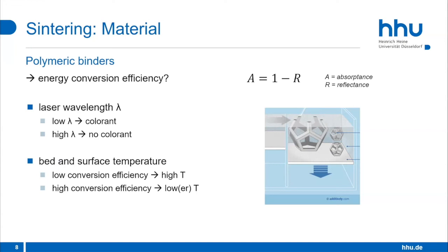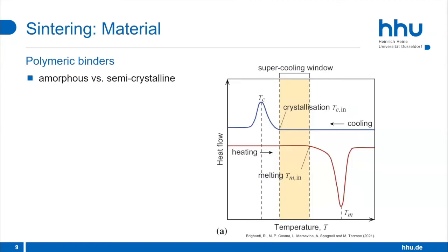And one issue that we also have with higher temperatures, or generally elevated temperatures in this process, is that the polymer might age if you heat it up for multiple hours, because this is the standard time for such a printing process. And then the enthalpy relaxation might be very strong. And it's very critical if you can then recycle the material after usage.